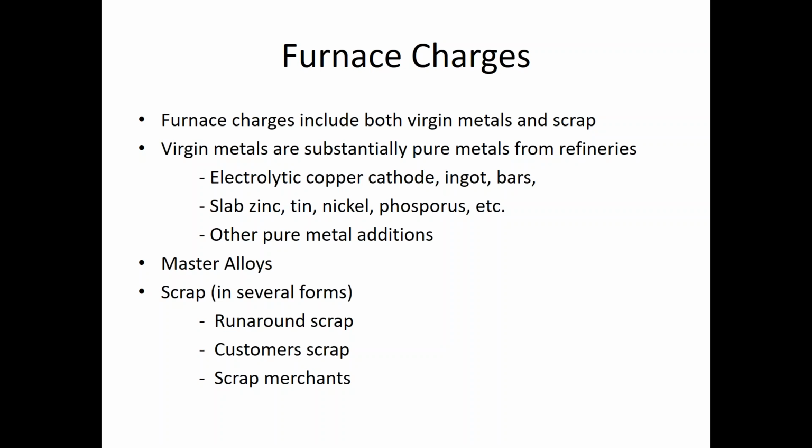Scrap is a very important component, however, and that's why I brought up the recyclability. Scrap can be in several forms. You have runaround scrap, you have customer scrap, and you have scrap from merchants. Runaround scrap is primarily from inside your mill. You have side trimmings, end trimmings, cuttings here and there, and all that material can be recaptured, sent back to